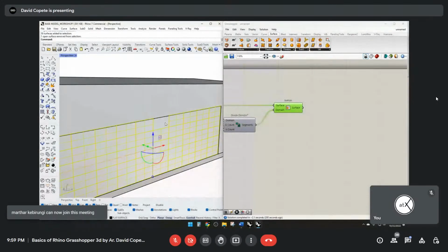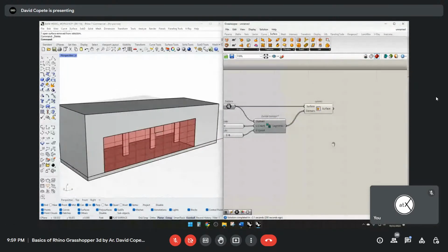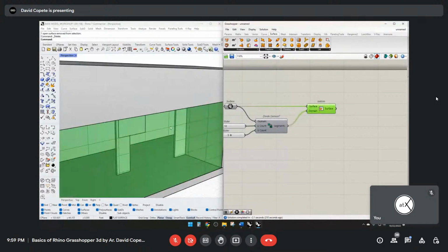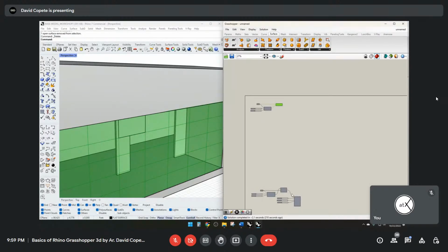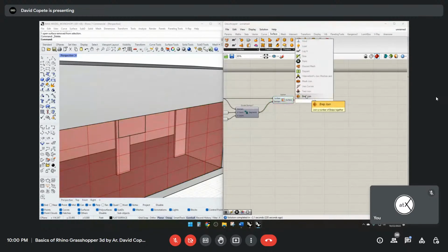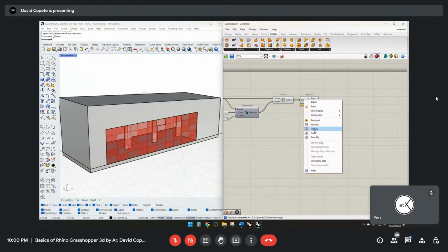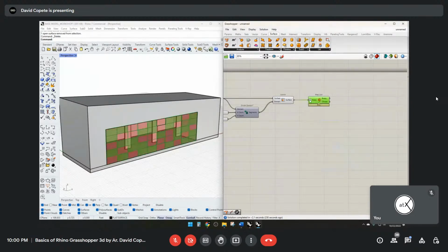Okay. That's not ideal, because then if I were to turn this into a wireframe, then we have two pipes on top. And that's actually the issue that we had with the Voronoi one, is that we have also overlapping geometry. And with this, we then need to join it. So I'll do the brep join, flatten the input, which means that they come in organized in one long list. Now I'll disable the preview here.